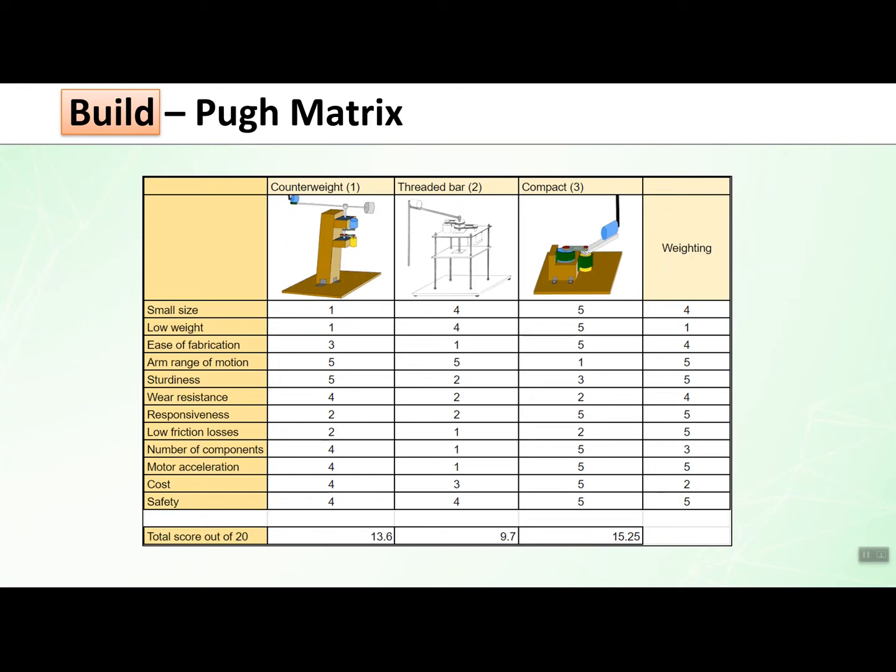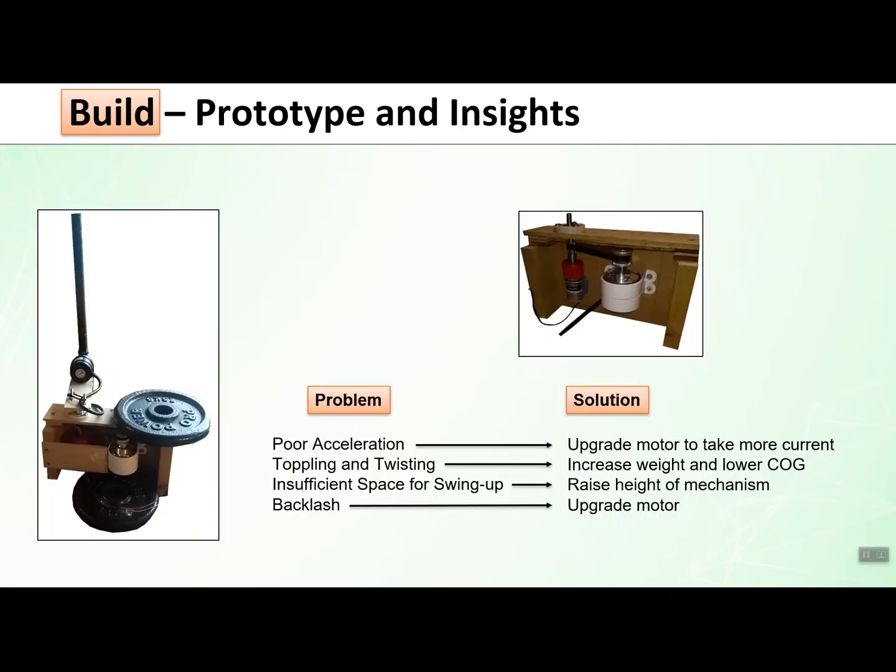The most important findings were that the simpler the design, the better, and that the motor should have a high responsiveness and acceleration. This meant transmitting torque directly to the arm, not through a belt, and Furuta, the creator of the rotary inverted pendulum, pointed out that the absence of a belt in a design is good because it's just one less component to model. Taking these things into consideration, a prototype build was made.